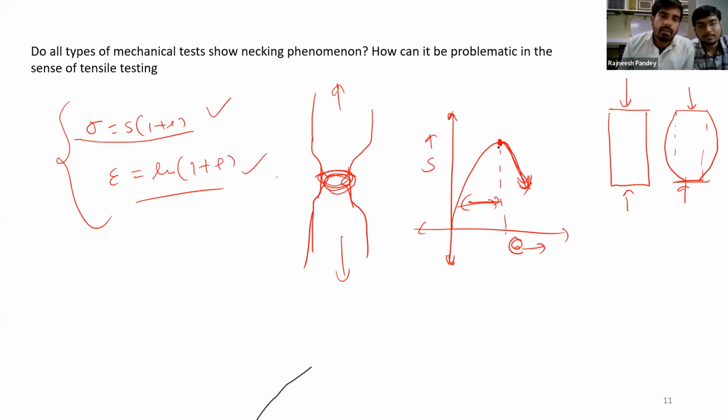Here the stress becomes very complex. It turns into a multi-axial stress system, called the triaxial state of stress. Initially we assume a uniaxial loading condition, but after reaching the necking point it is a triaxial state. That's why a lot of corrections are needed, like the Bridgman correction, which was also discussed in the module lecture.